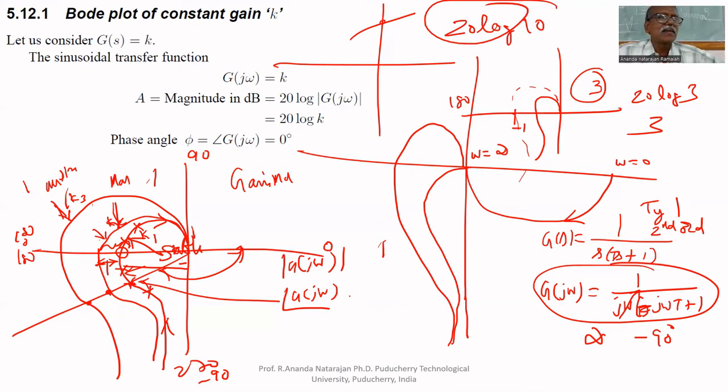So the factor is 3. In the first case, the gain of the system is 1. If we make the gain of the system equal to 3, it becomes unstable. Therefore, the factor is 3. In the second system, the gain of the system is 10. When it becomes 30, it becomes unstable. The factor is 3. If you multiply by 3, it becomes unstable. Therefore, gain margin is 3. The third system we have seen, initially its gain is 5. If it becomes 50, it becomes unstable. The factor is 10. If you increase the gain 10 times, the factor is 10. Therefore, gain margin is 10.